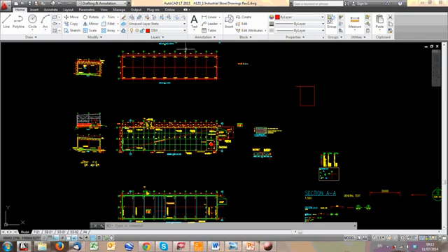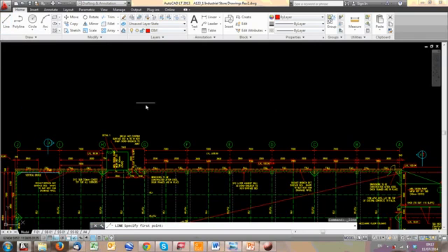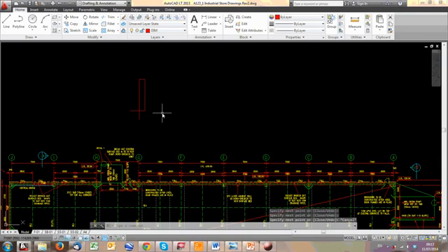Then, command lines are the way AutoCAD used to be used more, but it's still a very, very useful tool, and especially faster draftsmen like using the command bar, this bar at the bottom here. If I want to draw a line, from the ribbon, I'll just click line and I'll draw it. Press escape to stop using it. But I can also start creating a line from my command prompt. I type L for line, and you can see at the side there are other things that come up, such as L, layer, etc. Type L for line, press enter.